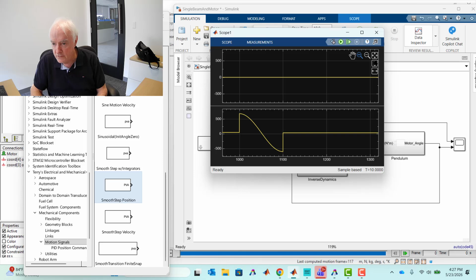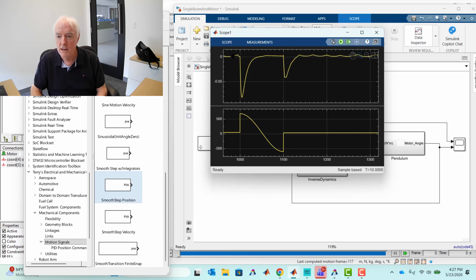Certainly if you consider the magnitude of the inverse dynamics, it's operating at maybe 550 Newton meters compared to something close to 0.05 on the PID. That might make you think it's doing everything. But I think these little oscillations are really important. I think the big oscillations that are occurring as the ramp begins and the ramp completes, this is really telling the story of PID and what it does really, really well.